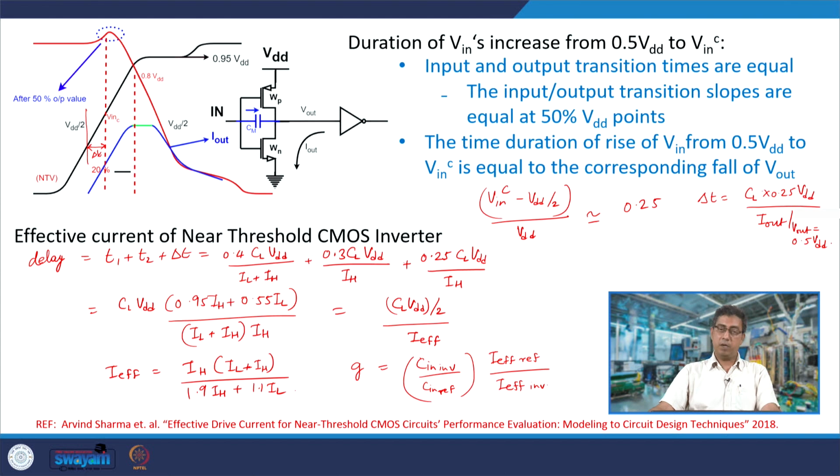used to estimate the value of effective current with changes in layout, with changes in temperature, with changes in supply voltage or mobility, etc. Because this effective current model is based on two DC current values at certain terminal voltages, it is an effective current model which can be used to consider variability in the circuit design itself.